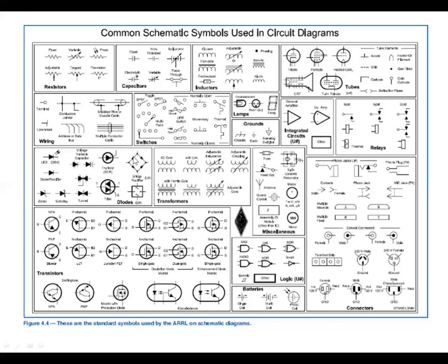configuration of 4 diodes. It's a bridge, and what that's used for is converting AC power to a pulsed DC. So it essentially takes the negative part of the cycle and makes it positive, so that instead of the voltage going below 0, it goes back up above 0.